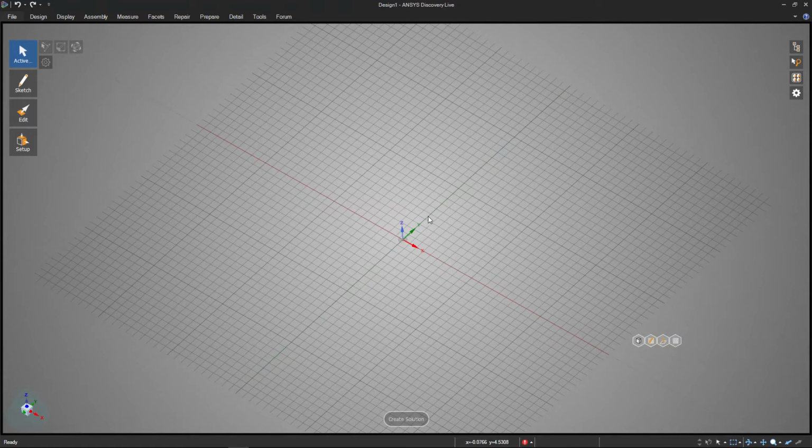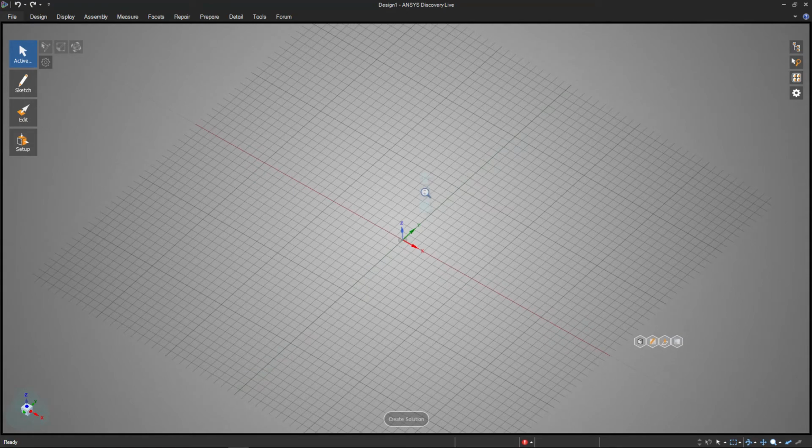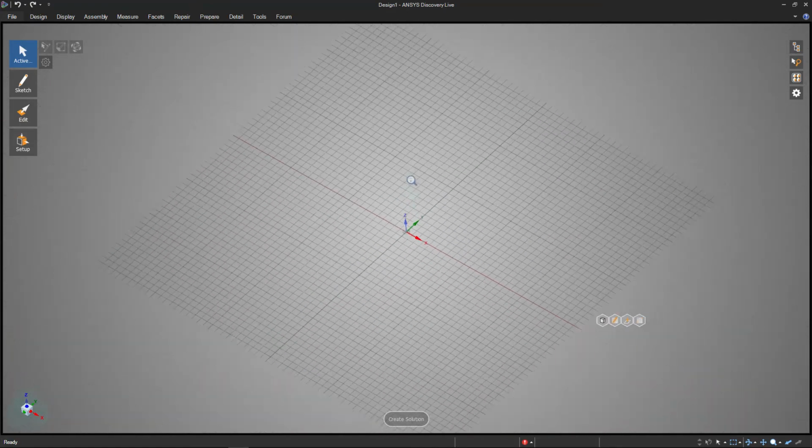The third and final thing is to zoom. There you hold down Control on the keyboard, click the center mouse wheel and hold it, and pull towards you to zoom in, push away to zoom out.